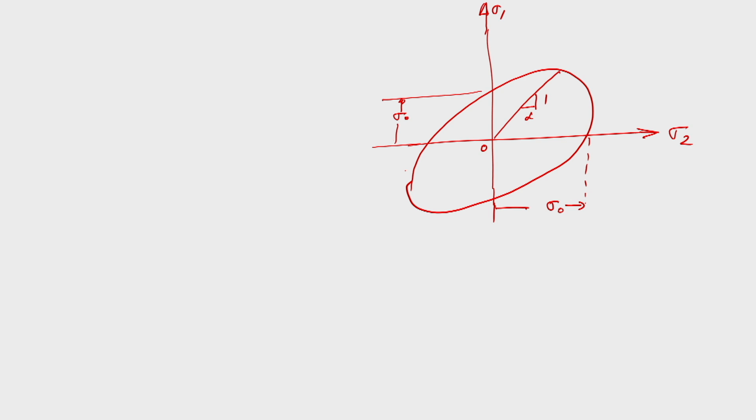Okay. So, this is the condition you can always take at any point on the strain history. You can find out what is the criteria for yielding which is taking place. Now, when the material is work hardening, you are plastically deforming it, this will again expand, but the shape will still remain the same. So, yield criteria helps to predict the stresses at which plastic deformation occurs in plane stress condition, where the ratio of stress in plane of the sheet to flow stress of the material is known. So, it will be able to predict the stresses.